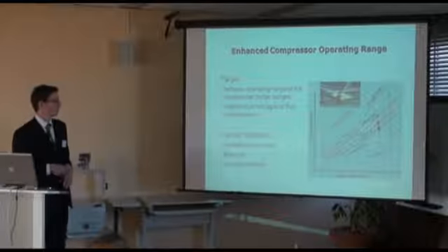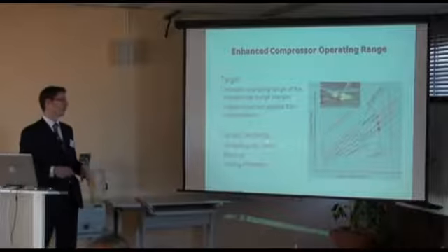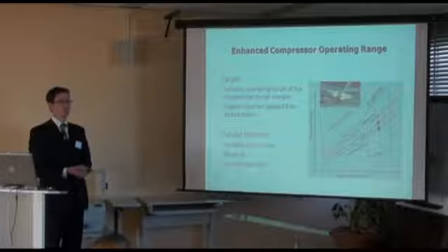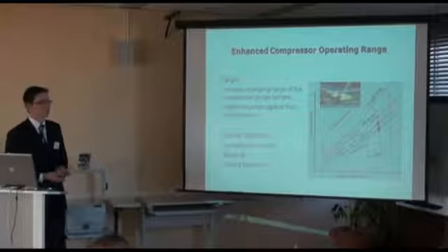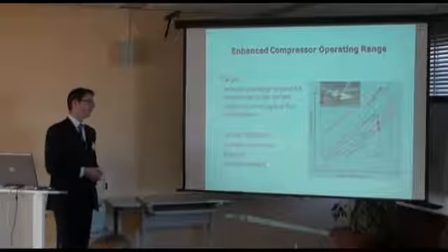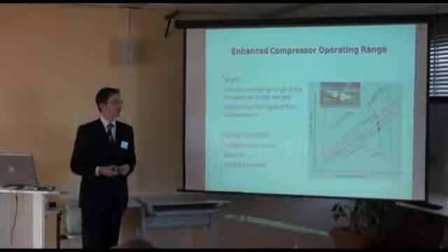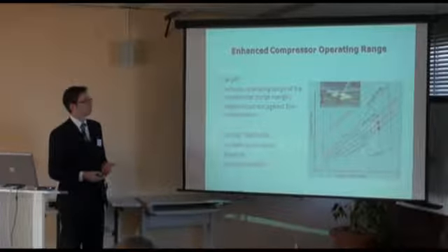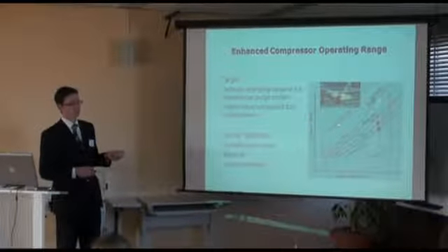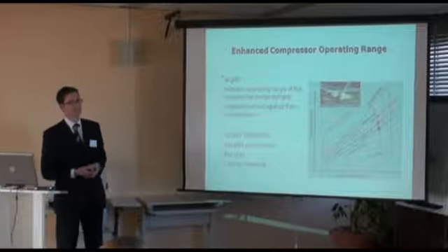Currently we have got, as I said before, variable guide vanes, which is an active technology, as well as bleed air already, but all these are scheduled and don't react on anything which goes on in the engine. And we've got a passive method which is called casing treatment, which are kind of grooves in the casing which increase the pressure ratio of the surge limit. They modify the flow structure about the blade basically.